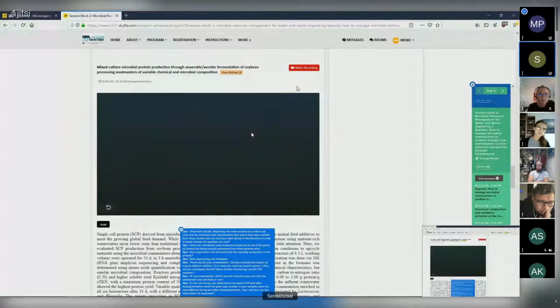And at the end of the day, you want to know what you use these numbers for, and you have to bring it back into risk. And using QMRA, you can look at different risks after different interventions and different stagnation times and bring that back to actionable items. That center was just reopened 2 weeks ago after installing 15-minute per day flushes at each of these group shower facilities, and with more than 90% non-detect either by culture and very, very low numbers by qPCR. So flushing can work if it's managed well.